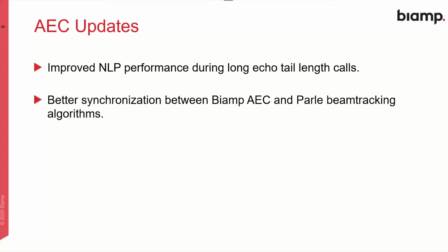We've also got better synchronization between the Biamp AEC and the Parley beam tracking algorithms. Since the Parley microphones are our Biamp product and they're sitting on the AVB network, we're able to set up back channel communications over that AVB network path between the AEC algorithm and the Forte or server DSP and the actual Parley microphone brain box out in the field.